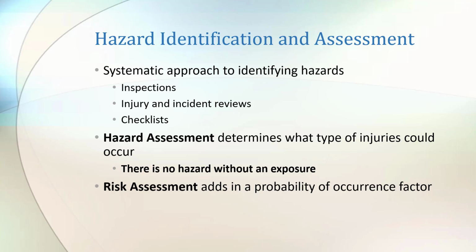We won't get into that. Just know that if you have a fan on the ground where I could reach my hand in and touch it, it's got to have a guard on it. Now, if I take that fan and I put it on the ceiling, and the ceiling is 10 feet tall, I have now guarded that hazard by distance, and I've taken away an exposure.